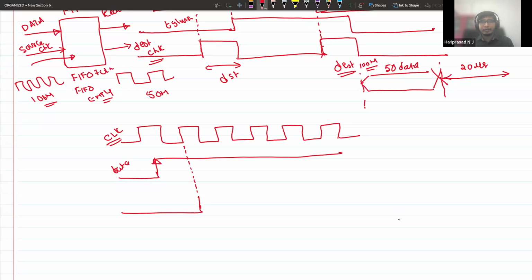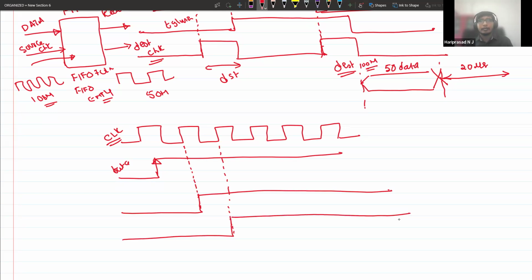First we synchronize using one flip flop, one clock cycle, and in another clock cycle you delay. So now, what operation do I need to perform between A and B to generate one pulse wherever a positive edge is there?